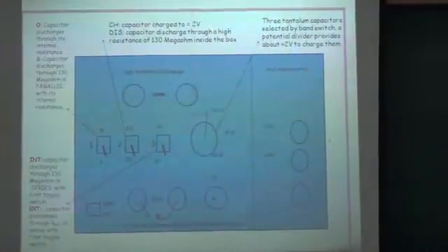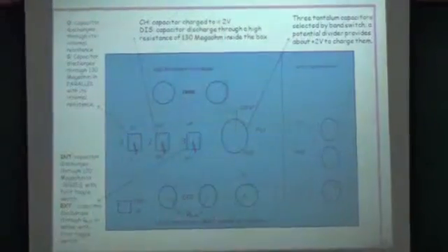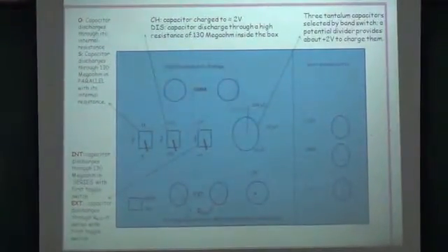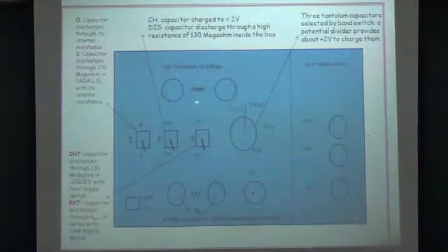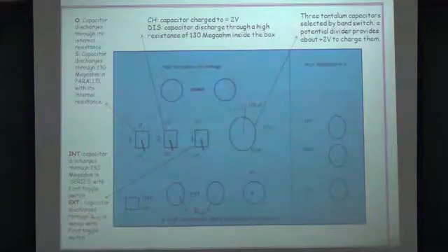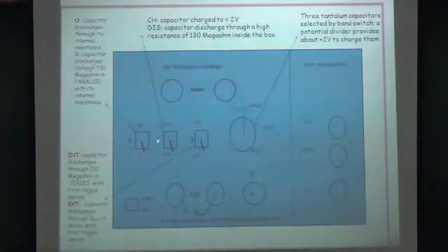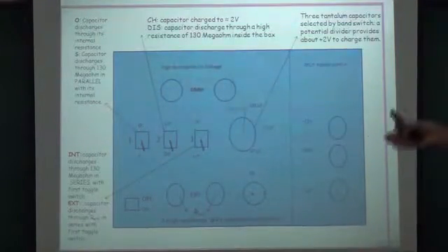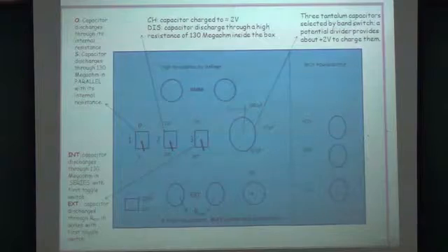We discussed, in fact, that to measure voltage the resistance of a voltmeter must be infinity. But here we are measuring a very high resistance. So there is a problem of impedance mismatch, because this resistance is comparable with the resistance that we are going to measure. So what we have to do, we are going to feed the voltage drop across the capacitor to our buffer. The buffer basically transfers the signal from the higher impedance side to the lower impedance side, and we can measure the voltage by using this digital multimeter on the lower side. So the problem of measurement is over.